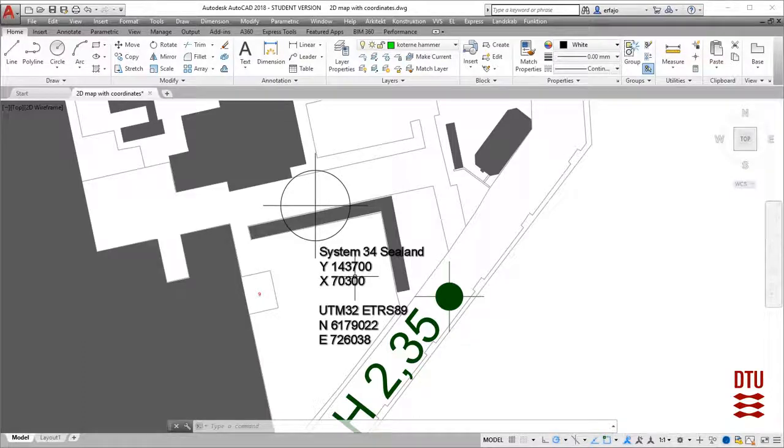They are the same numbers I'm going to use inside Revit, but you must remember that survey drawings or survey files will be in meters, and we are working in millimeters inside Revit, so you have to convert this when you set the points.